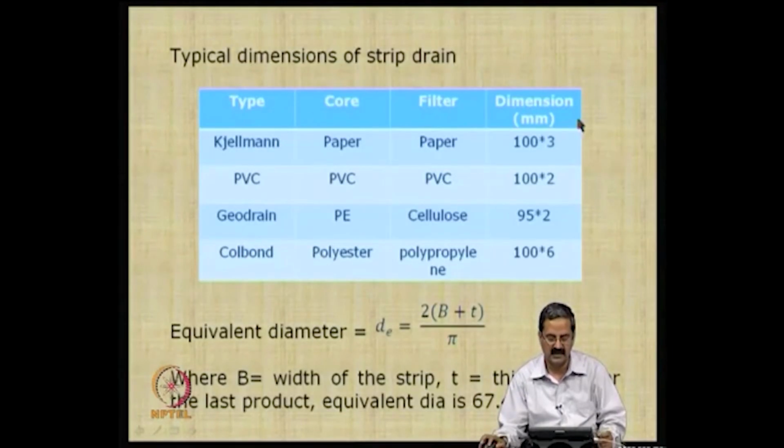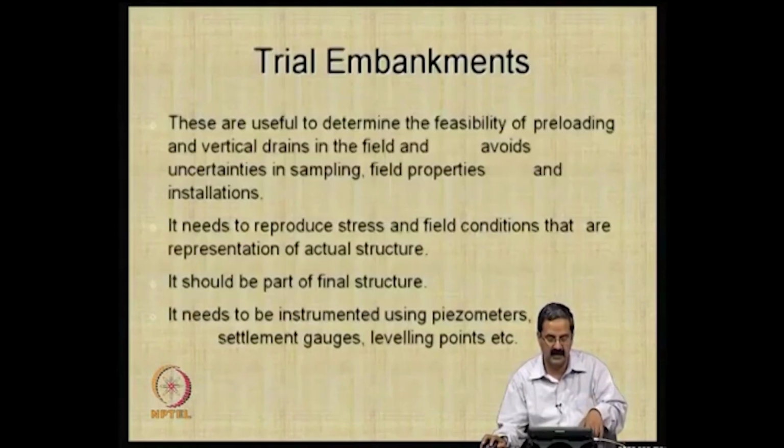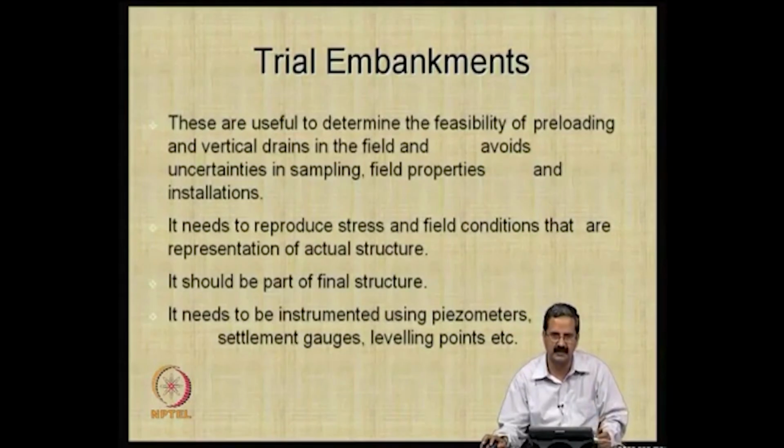As I just mentioned, these are some examples of the PVDs. You can calculate the effective diameter with this sort of expression, and once you know this D_e, you can also calculate the effective drain influence area. There is another expression depending on the pattern. Once you have those patterns, you can go ahead with the design and complete the process. The design is similar, but the advantage is that they are much more scientific.